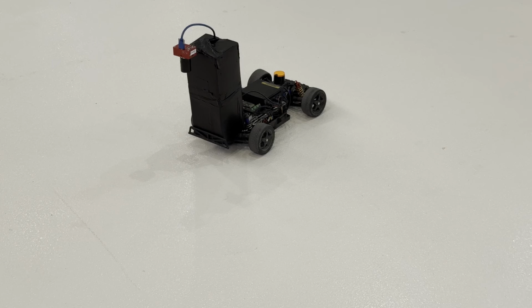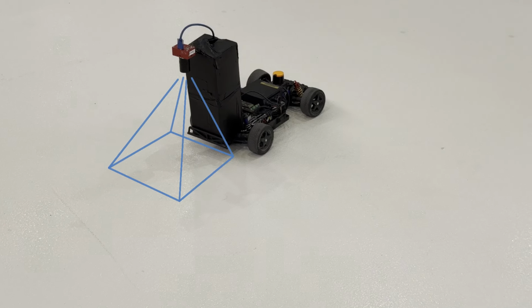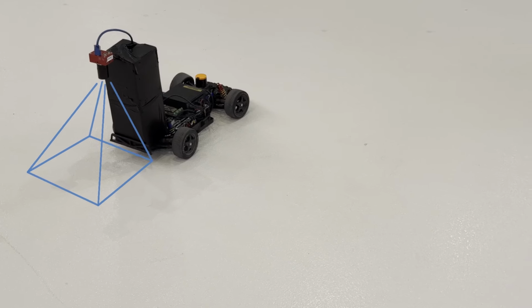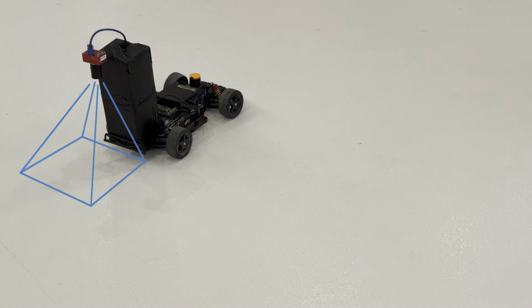For this reason, we present an approach where the camera is pointed downwards such that it sees the ground below the car. Looking at the ground is interesting because from the perspective of the camera, it can be considered a single rigid body that is also moving in 2 dimensions, but in exactly the opposite direction of the vehicle.